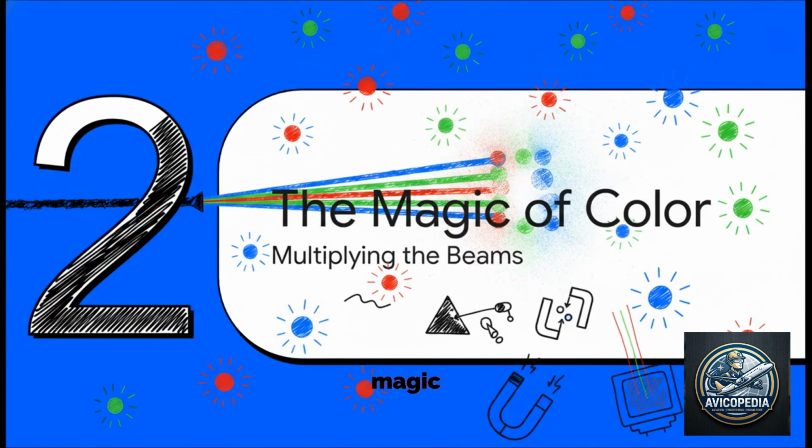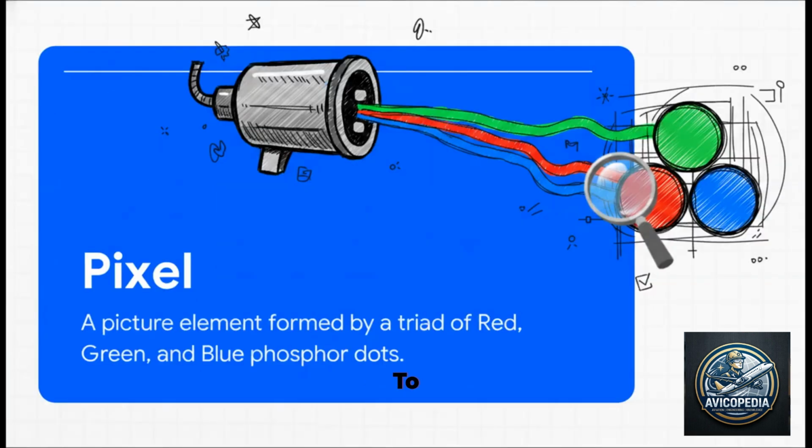Section 2. The magic of color. Multiplying the beams. To get a full picture, we need to define what a pixel actually is in the physical realm of a CRT. We toss the word pixel around all the time today, but here, it's a very physical, tangible thing. A pixel, or picture element, in a color CRT is formed by a triad. Think of it as a specific pattern of 3 phosphor dots coded right onto the screen. These dots are doped to emit 3 primary colors: red, green, and blue. This RGB triad is the fundamental building block of the entire display.